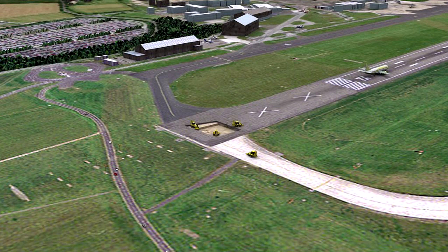However, the two most common reasons for TORA to be less than the length of paved surface is either because there is a variation in the runway surface strength, or because there is work in progress. When the threshold is not at its usual position on the edge of the paved runway, it is described as a displaced threshold.